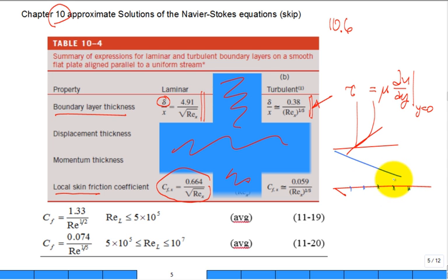It's going to be coming down. It's not a straight line, but it's coming down as I go further away from the leading edge, measuring x. You also get one experimentally in the turbulent region. So it goes down, then it kicks up, and whoops, that's a bad rendition, then kicks back down again for the local c_f of x.